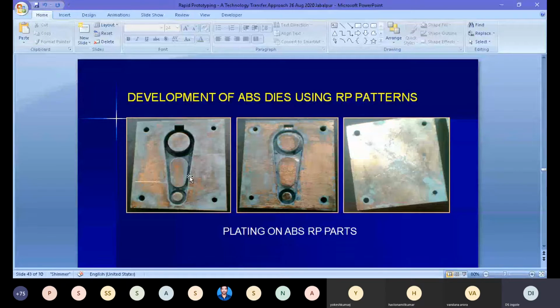because of the porosity. And when you want to metallize these plastic parts, some chemical treatment of the surfaces is required. And when these components are dipped into the chemicals, the chemicals get entrapped in these products, and then you cannot have metallizing on this.